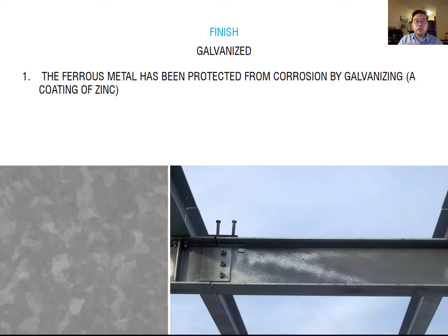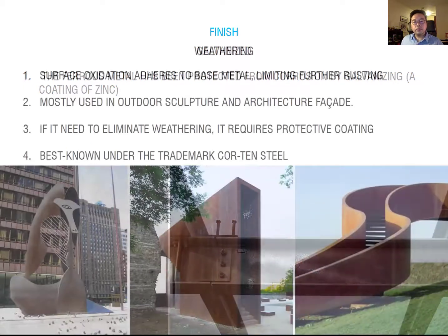That's why it is mostly used for the structure member, but a recessed structure member. It is kind of covered by the finish material. No one actually can see this material. So it's more about being recessed behind the finish material, but still having good protection against corrosion, and also the price is cheaper compared to the other steel materials.